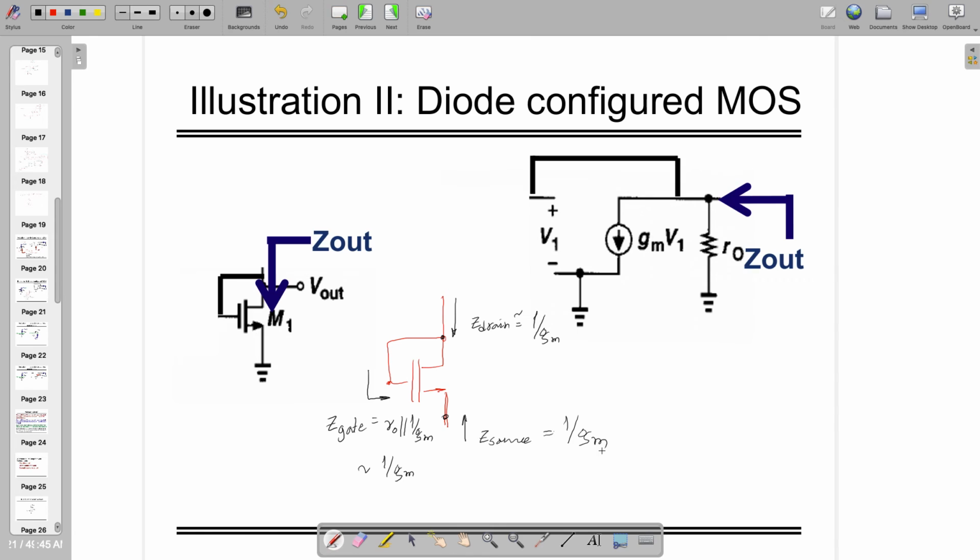And this is also the case for BJT. If you want to solve, you can solve that. If you're looking into this one, it's r_pi in shunt with 1/gm in shunt with ro, whereas 1/gm is the smallest one, so I can approximate that to 1/gm. And same for this side, same for this side. So everywhere it's 1/gm, right? So this is one thing.